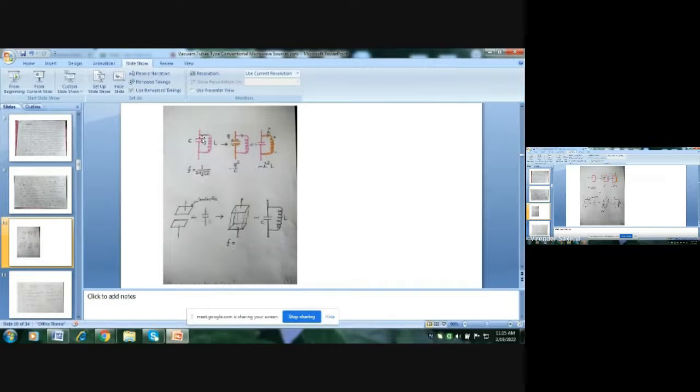At low frequency, the field remains constant when electrons interact from output to input, and we can maintain the condition of positive feedback. But at high frequency, the field of this tank circuit changes rapidly, and therefore it is difficult to maintain the positive feedback conditions for every cycle. So it is difficult to obtain microwaves by using conventional circuits.